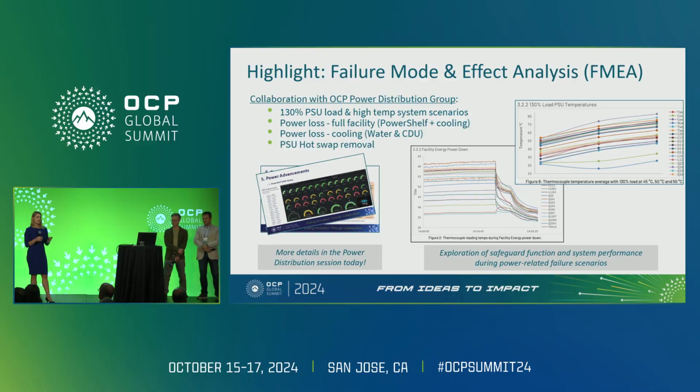The last thing I'm going to show is a highlight for me, which is we identified a couple of key scenarios related to the power supplies. We know that power supplies are starting to be immersed, and we saw this as a place where potentially some type of abnormal operating condition might lead to a failure. The fluid might get overly hot. Certain safeguards that are designed for air might not be applicable. There might be a risk of auto-ignition or some similar type of failure.